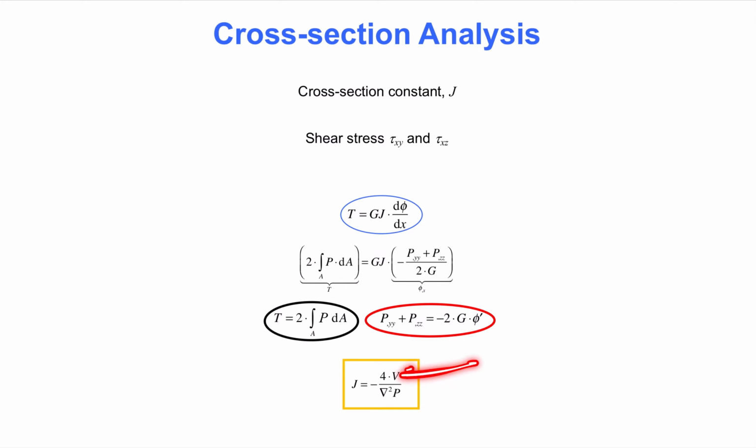The main objective when solving practical problems in St. Venant torsion theory is the determination of the stress function. This is done for different cross-section types in the notes and examples posted at terje.civil.ubc.ca Toolbox and in a short course posted there on cross-section analysis.